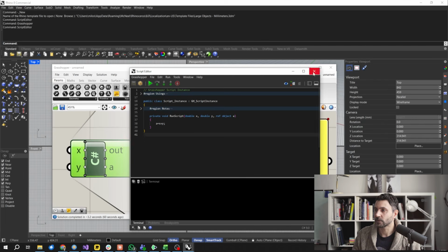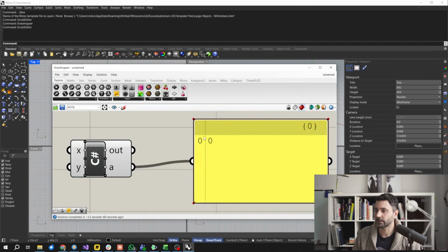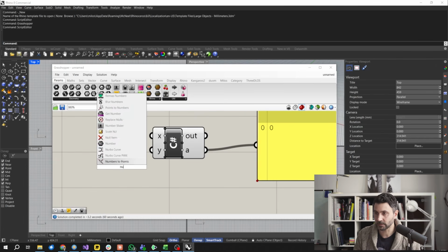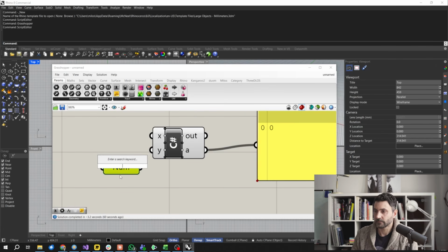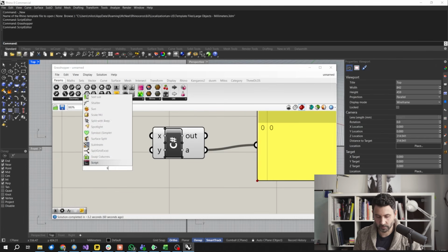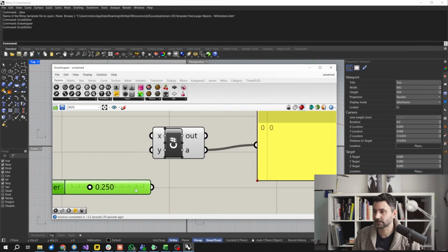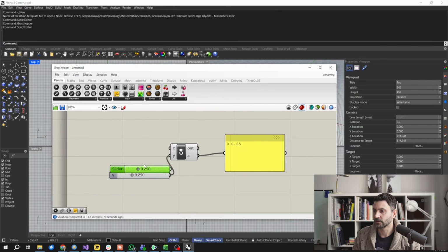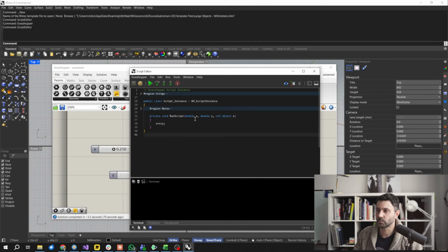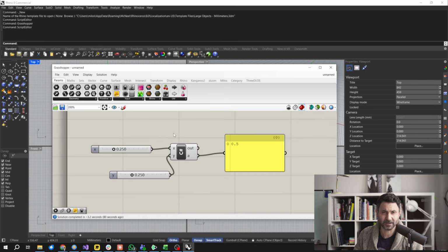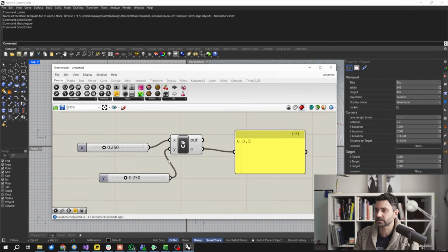And then you will get here a number. Of course, we will again need some numbers. And you know, in Grasshopper, you also have these number sliders that make it a little bit easier to do something. But you see, we created our own addition. I can change here to integer, and any type of variable, and Grasshopper will, I think, automatically help me see what kind of objects I'm putting in.